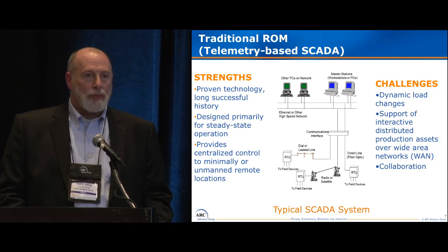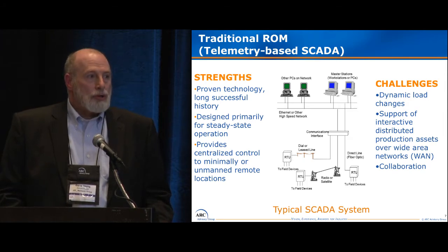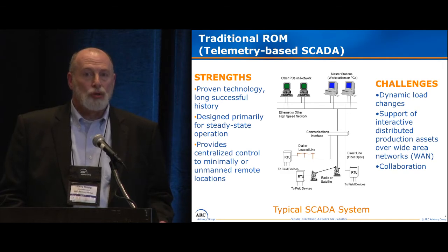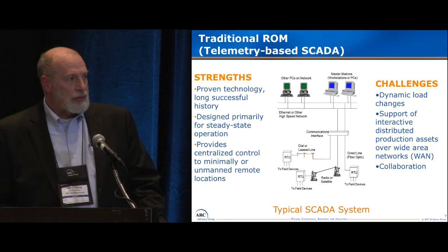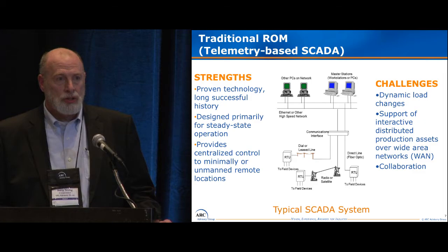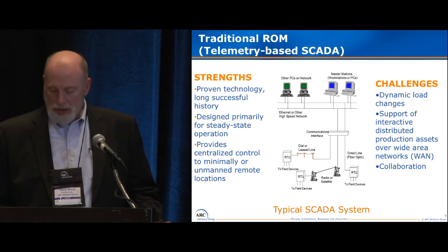So traditionally, remote operations was thought of in terms of SCADA, supervisory control and data acquisition, where we had what we call remote terminal units and then master terminal units back at a central location. And this certainly served the industry well. However, there were some drawbacks to it. Typically, it was quite slow. There were lags in the communication. It really wasn't real time. It wasn't really robust in the communications. And so now we're looking to take this structure, if you will, the remoteness, to the next level.